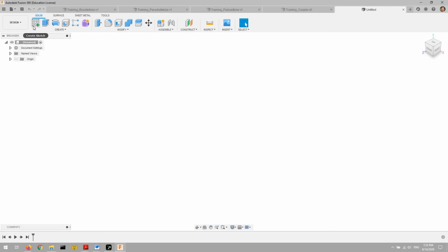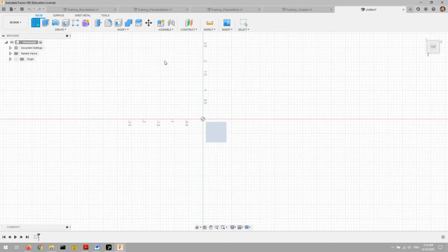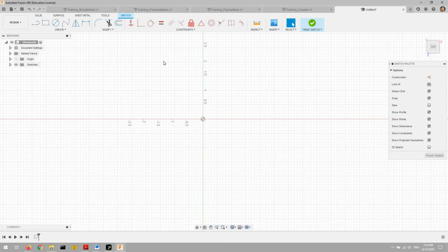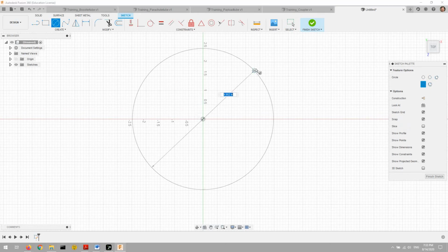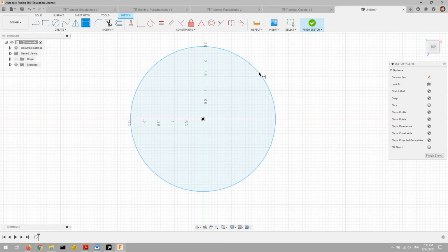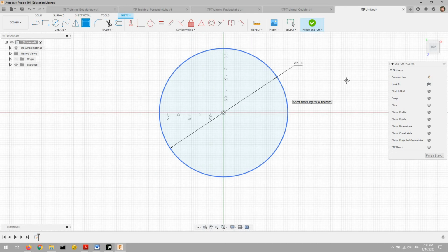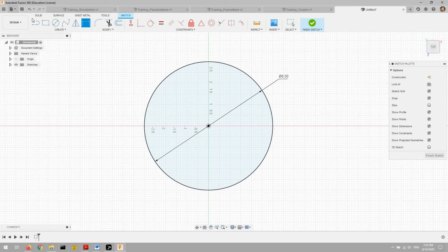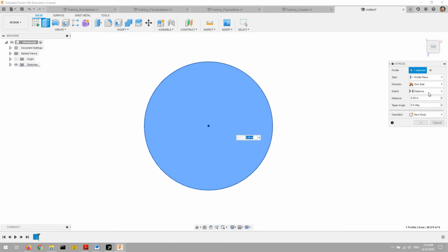Next will be the Avionics Bay. Again, this is a cylinder, but this one is going to be interesting because it's going to have a ring around the outside. But to begin with, let's just create a solid cylinder this time instead of a hollow one, which is even easier to do. Just define a single circle, and that's going to have a 6-inch diameter because it's going to be going inside the other tubes. And extrude, chooses that whole face.